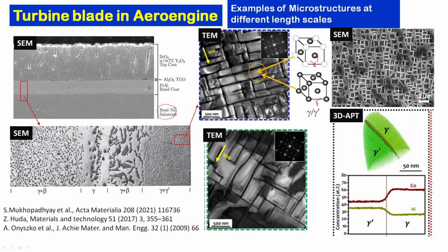So therefore if you are using it at high temperature, there will be thermal mismatch, and this can lead to stress generation at the interface, and that can actually lead to failure. So that is why you have to put an intermediate layer which is called a bond coat, you can see here, and this bond coat has a composition which is basically platinum, aluminum, many other metals, nickel, chromium also would be there, and this bond coat, once it is subject to high temperature, can form a thermally grown aluminum oxide. That is how this gradient of thermal expansion coefficient can be created from zirconium oxide to aluminum oxide to bond coat to the superalloy.